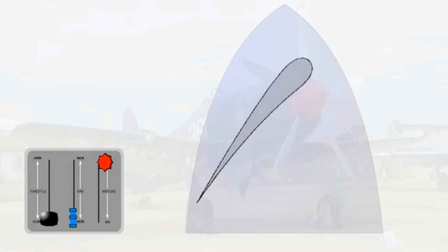A single-engine airplane fitted with a constant-speed propeller will not have a feathering capability as such. However, following engine failure, drag can be reduced to a minimum by moving the propeller pitch control to the fully coarse position, as shown here. In a steady glide with no shaft power from the engine, the throttle closed, if the propeller pitch is increased by pulling back the prop lever, the aircraft lift-drag ratio will increase. This will decrease the rate of descent. The RPM would decrease because of the reduction in negative propeller torque.